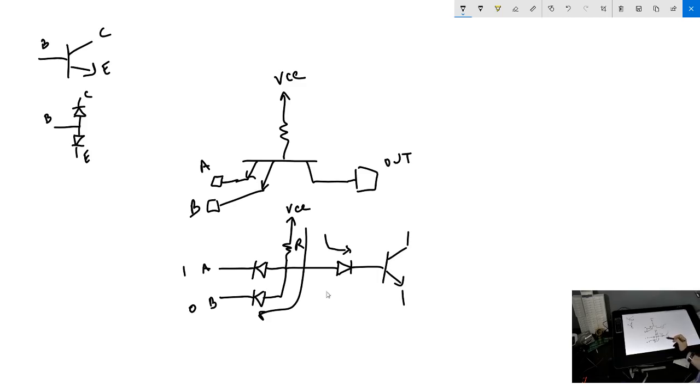So this diode is now not being forward biased, because this is now at ground. This is at something like 0.7 volts. And there's no way that this node over here can go below ground or be at ground, because there's still this junction over here. So there's no current over here. So basically this thing's off. So you can consider the output a 0.